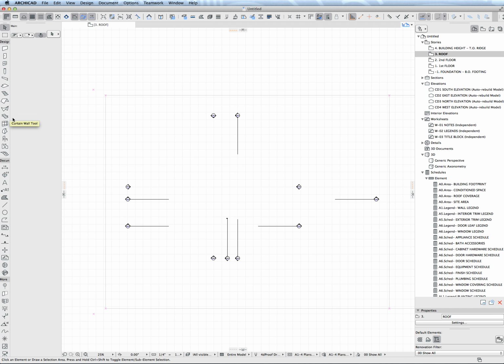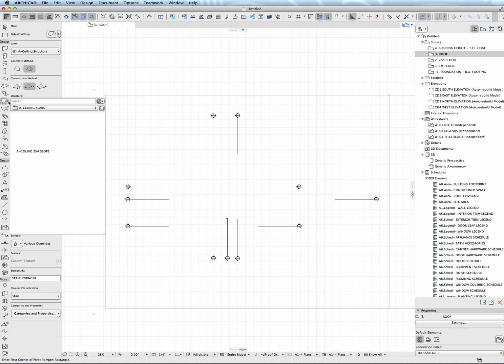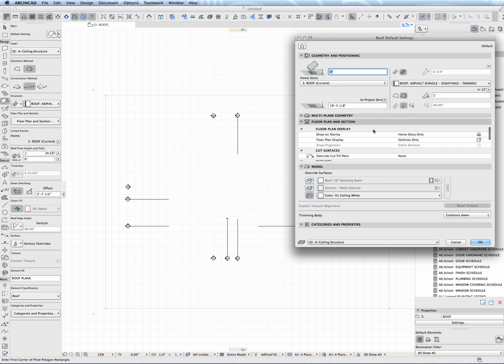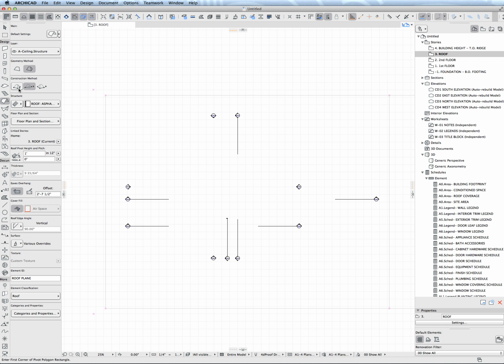First of all, I am going to start with just a basic roof here, and if I pull from the roofs I have available in my template favorites, I can get to just a basic shingle roof. And then looking at the settings here, I can go to a multi-plane roof or a single plane roof, individual planes. Typically I like to work with the single plane roof, but I'm going to show you something really quickly with the multi-plane roof. I'm going to say OK here.